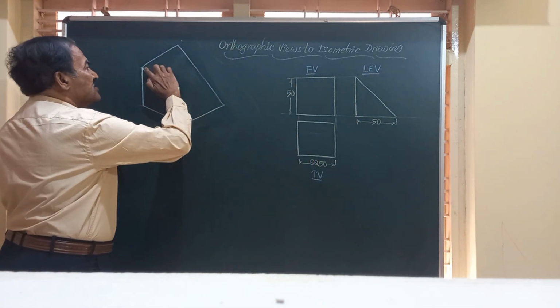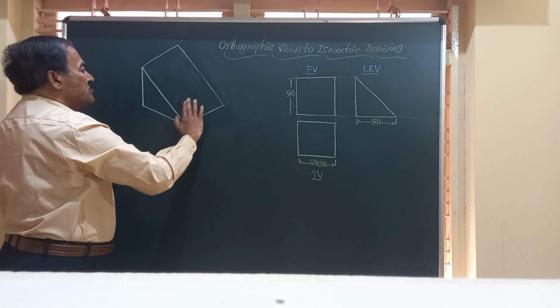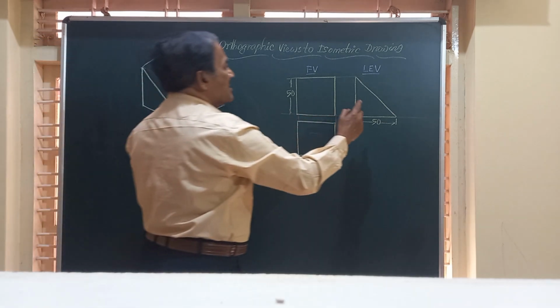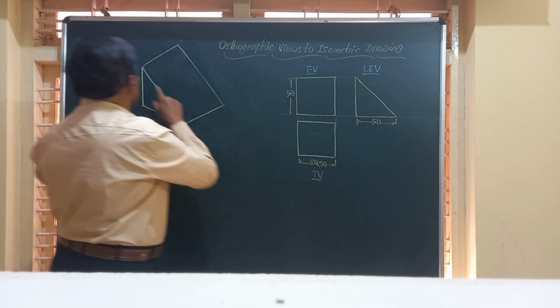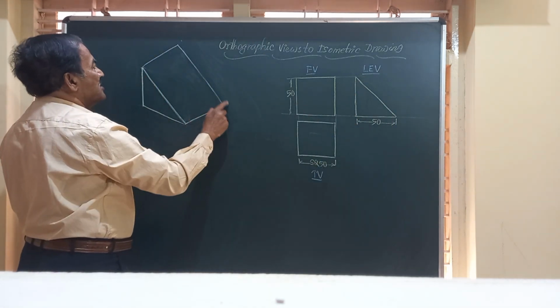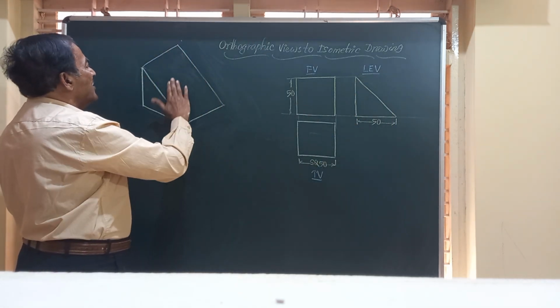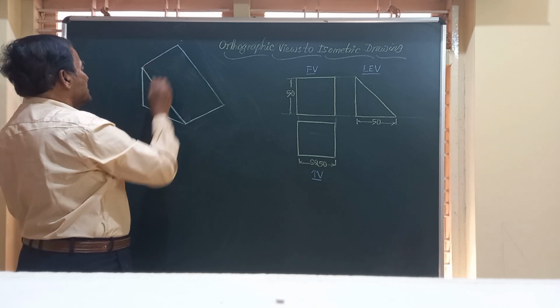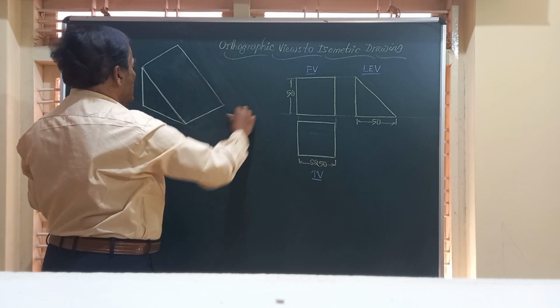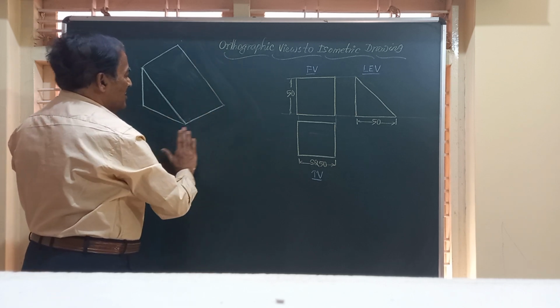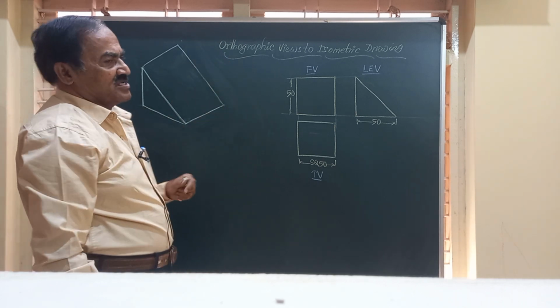And this surface or this rectangular face you see here is representing this line. So this has got 4 points, 1, 2, 3 and 4 corners. And we have removed all the construction lines from here because that's a convention followed in all isometric drawing or isometric projection.